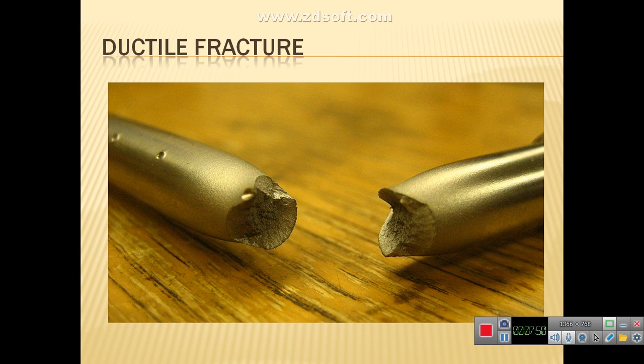Ductile fractures sustain plastic deformation when the material contains relatively hard inclusions which do not deform at the same rate as the matrix. Voids are nucleated and accommodated incompletely. The nucleation may even involve fracture of the inclusion.